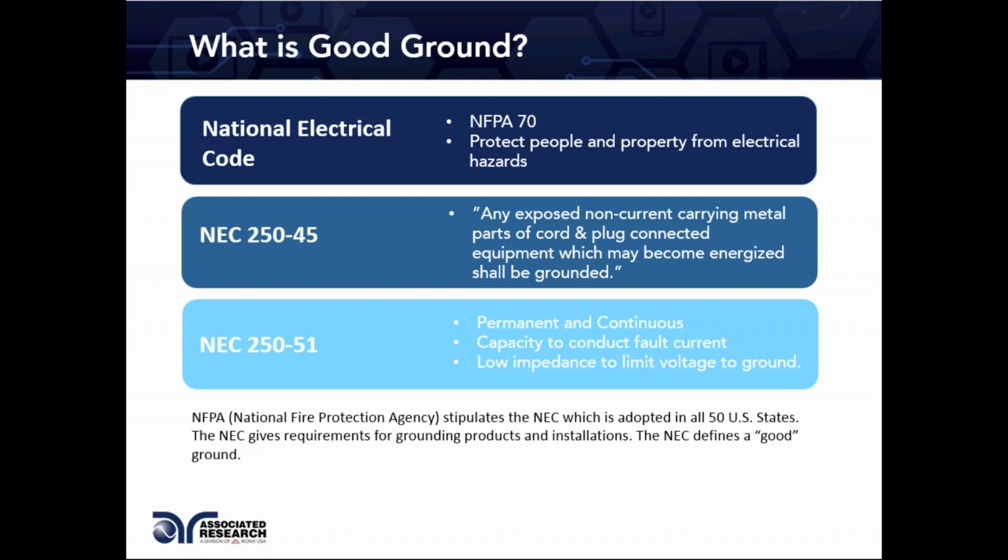The other thing I forgot to mention is that ground also protects against fires, because anytime there's a short circuit, high amounts of current can flow in a breaker, and if it's got a good ground, it will take care of all that fault current and route it safely back to earth ground, rather than it heating up the breaker and resulting in a fire.